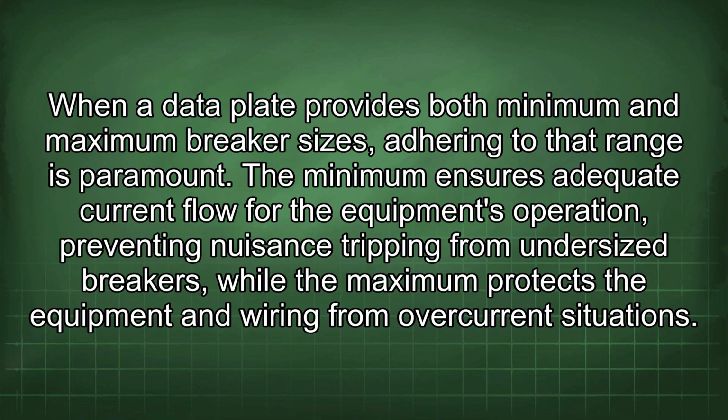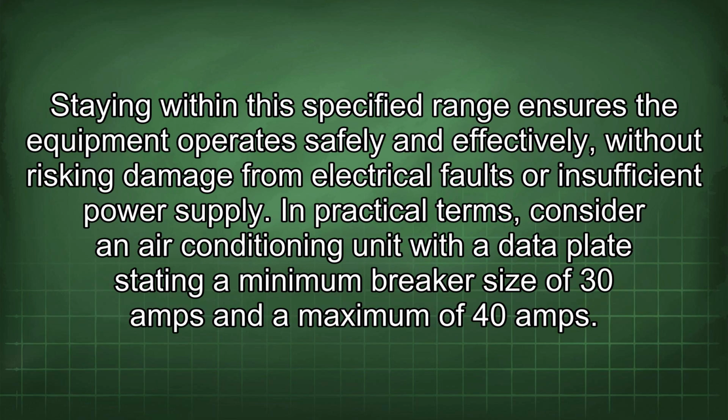When a data plate provides both minimum and maximum breaker sizes, adhering to that range is paramount. The minimum ensures adequate current flow for the equipment's operation, preventing nuisance tripping from undersized breakers, while the maximum protects the equipment and wiring from overcurrent situations. Staying within this specified range ensures the equipment operates safely and effectively, without risking damage from electrical faults or insufficient